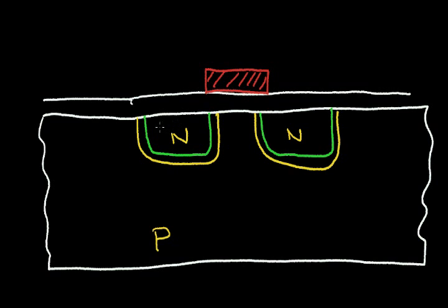And let's presume that this N region is at 0 volts, and this other N region is at 0 volts. And I increase the voltage on this electrode. I'll put a battery here to this 0 volts. And as I increase this voltage, I get an electric field in this glass region, in this insulating region, that's a little reminiscent of the electric field that is in the p-n junction. Now, as I increase this battery voltage V, this electric field becomes stronger and stronger.